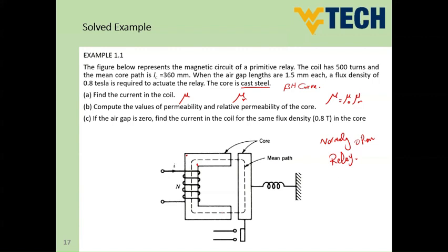So does it mean, guys, the current during the stroke of the relay will be the same current, 4 ampere, 4 point something? Actually, no. If we draw a relation between the current and the x, and consider x here, in this portion x equals 0, and this is the direction of x. In this case, guys, the current will reduce.